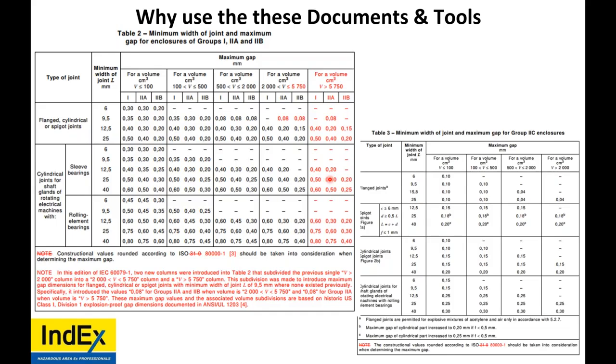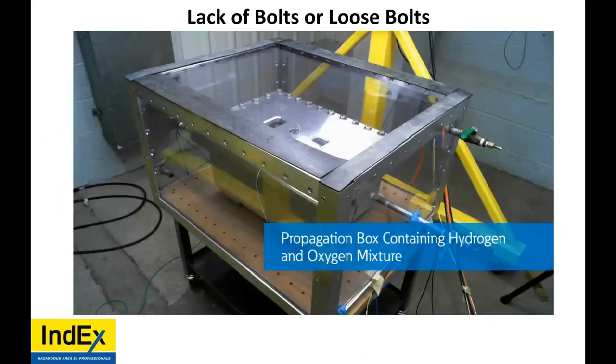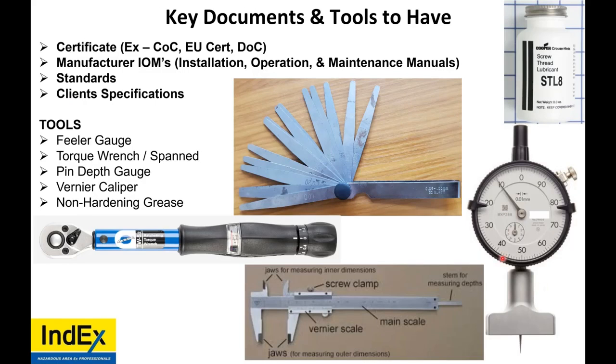Well, it wouldn't be going over the 0.2, it would be exactly 0.2. So think of that gap. If you make any valleys, you're making the gap wider. You can at least measure with a pin depth gauge how much wider your gap is, the valleys, the scratches, and with the vernier, you can measure how long it is.